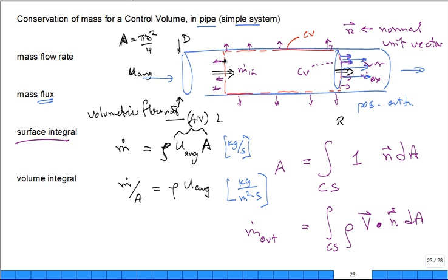Okay. So this would all be positive outflow. If I come over here, the unit outward directed normal vector we already talked about. It's pointing in the negative x. But guess what the velocity is doing? It's in the positive x. True? What's the angle between them? 180. I do the cosine of 180 degrees. Not a positive one, but a negative one. So it's the magnitude, negative 1. It's representing not an outflow, it's representing a negative outflow, which is an inflow. Or I should say, it's a negative outflow, hence it's an inflow.